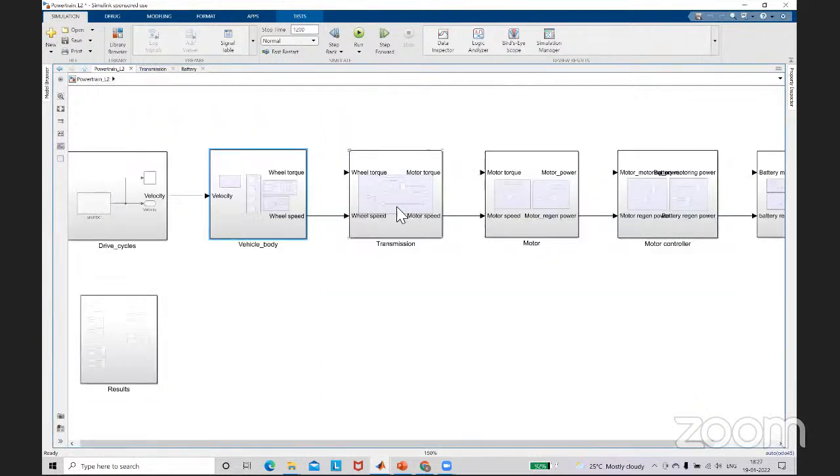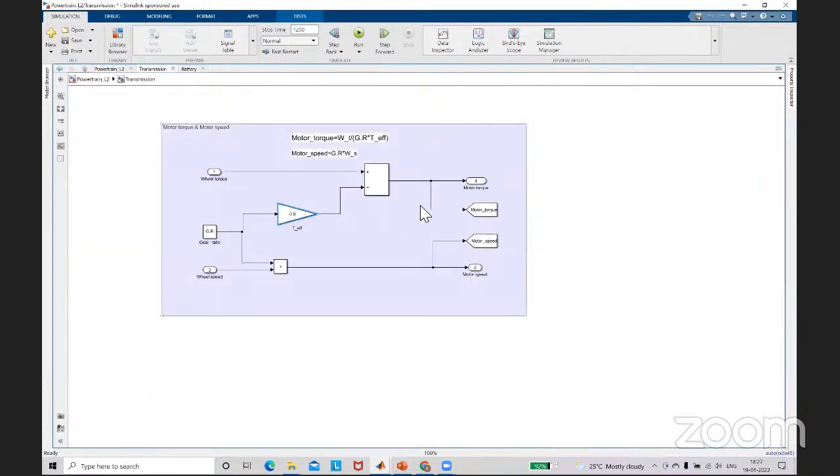So with this, you are going to get the wheel torque and the wheel speed. If you know the transmission modeling, with the transmission efficiencies and the gear ratios, which will already be the design values, or you can also get those values by modeling based on our requirements. It will be designed based on our torque requirements and the speed requirements, these particular gear ratio values.